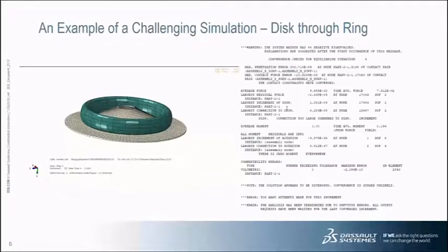So what do we do? Well, we can go look at the Abaqus message file to see what was going on in the numerical calculation, and we see interesting messages about negative eigenvalues, solution is diverging, but it looks like the contact is okay. You can see contact constraints are converged, which sounds good, whatever that means. So perhaps this is not a contact issue.